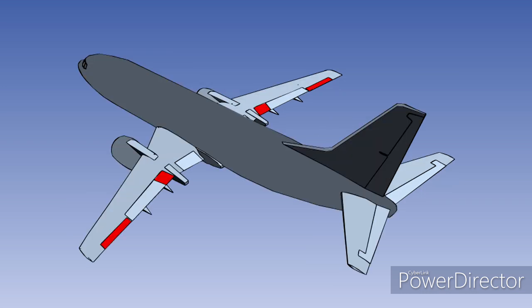Alternatively, two sets of ailerons are often fitted, one set at the wingtip for use at low speeds when the forces involved are low, and one set inboard for use at high speeds when the forces are greater and could cause greater structural distortion.